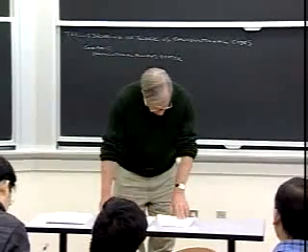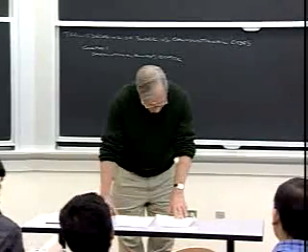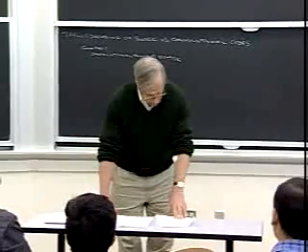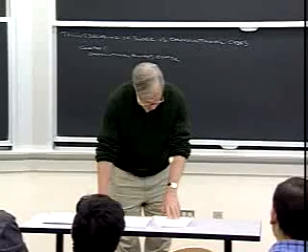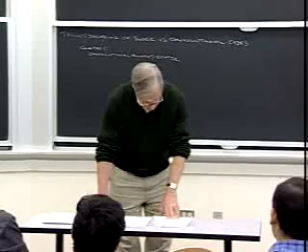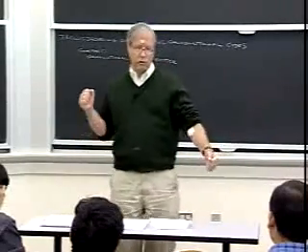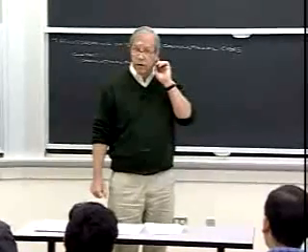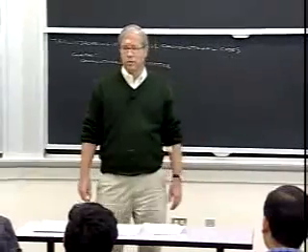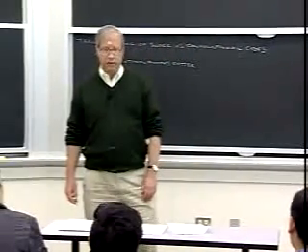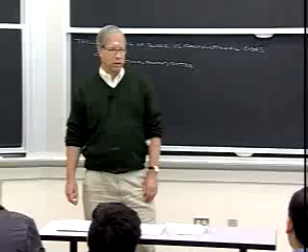Another head-to-head comparison might be with the 32-16-8 Reed-Muller code. That's a rate 1/2 code. It's a very good one. It's known to be the best with those parameters, NKD. So what's its nominal coding gain? Anyone? It has rate 1/2, minimum distance 8. Its nominal coding gain is? Hello? 6 dB. You take the rate times the minimum distance, 1/2 times 8, you get 4. So that's the nominal coding gain, factor of 4, which in dB terms is 6 dB.